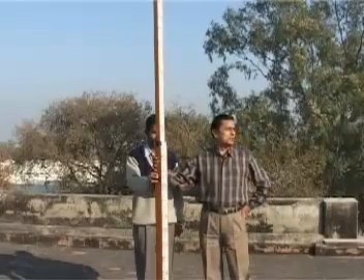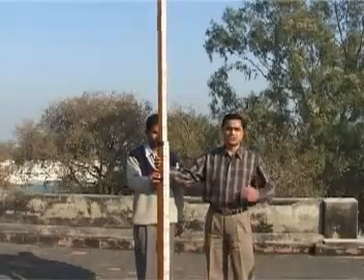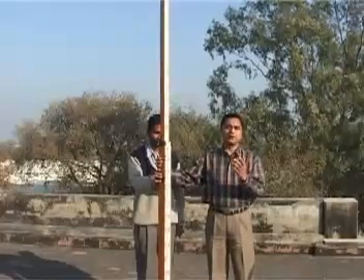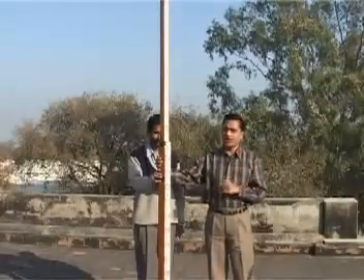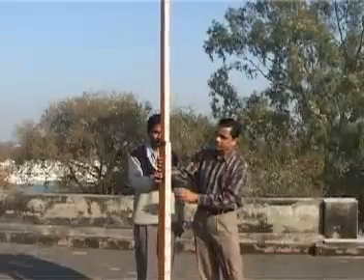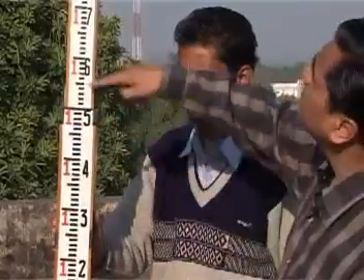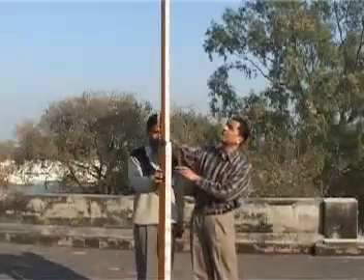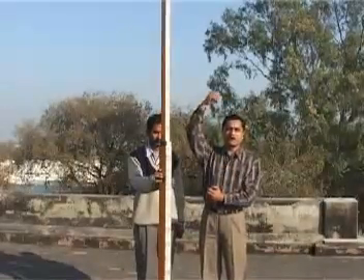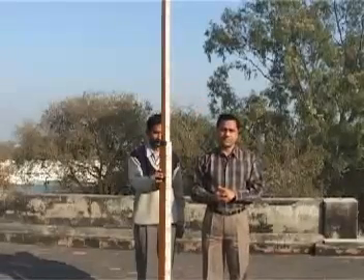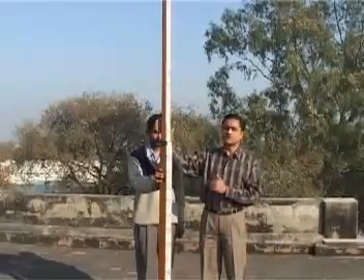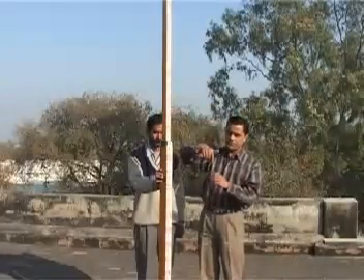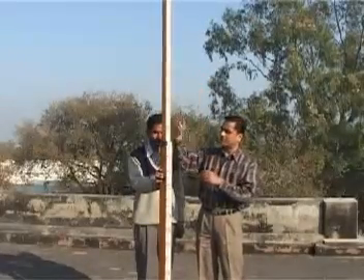Now this is one staff. Now staff, as we are saying, is a vertical scale. Using our level, we sight the staff and we read the reading. Now as you can see here, this is the big staff, and we can fold it or unfold it, and the total length of it can be increased up to 4 meters. There are different kinds of staffs. This one we say telescopic, because one staff will get into the other one.